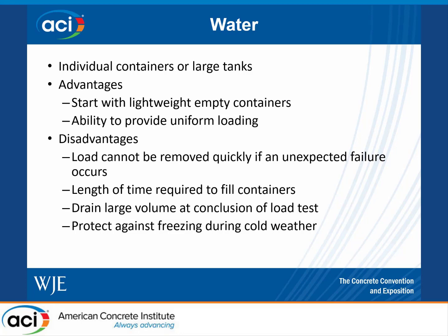With water, again, you can go with individual containers or large tanks or anywhere in between. One of the key advantages is you start with very lightweight containers. You can bring this material out to the site easily. You can move it very easily before you apply the water or fill up the containers. And you can very easily provide a uniform load in the test area.